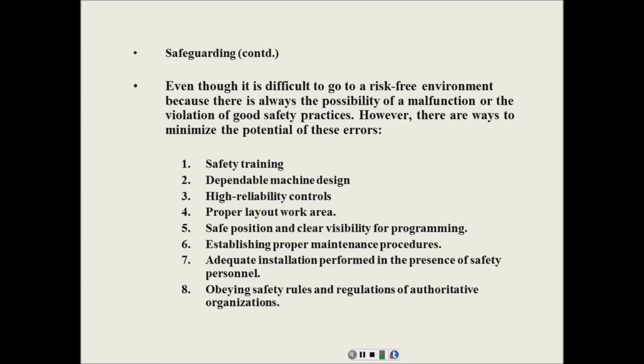Y'all understand that? On the Kuka, if you put it on regular teach, you're limited to 250 millimeters per second. But when you run your program in manual mode, it's going to be 30% of 250 millimeters per second, which is nothing, right? Understand? So you can run yours at the same speed as everybody else.